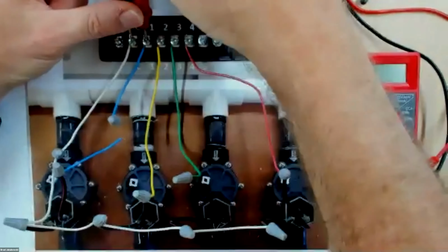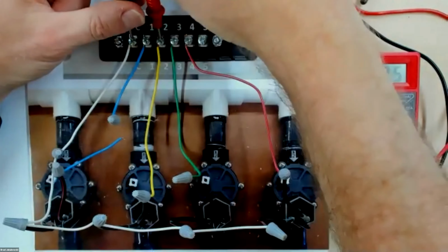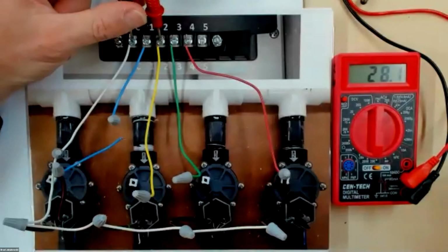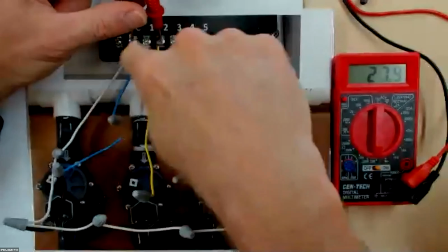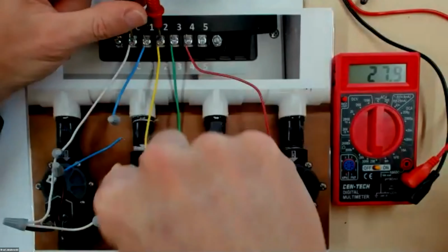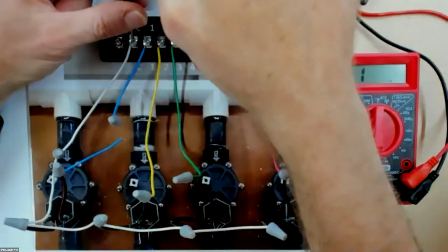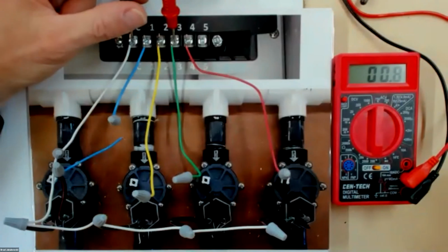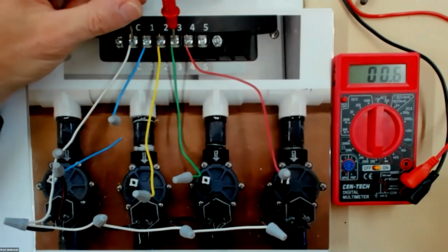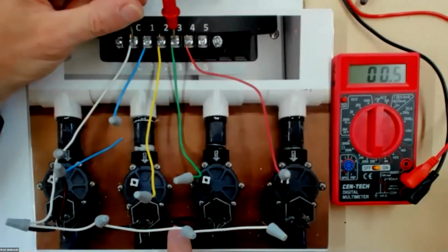let's check and see what's going on with station 2. So go ahead and check station 2. And hopefully you should get some kind of a reading. If you think about it, this circuit is broken, but this circuit is still traveling all the way through over here. So that circuit's good. Circuit 3, this one here, it's a short, but otherwise it's operating correctly. If we would have had a resistor there, we would have the standard reading. So that was the reading that we expected there. So that one's actually working correctly. So station 3 is working okay.